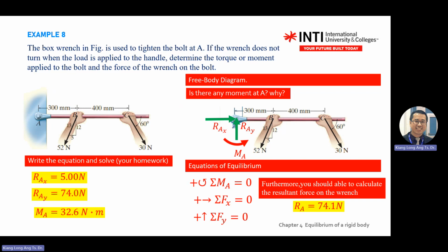We'll give you further instruction. You need to find resultant in your answer. So after you find Rx, Ry, square this one, square root, you get the resultant. Use the tangent theta, inverse the tangent, you get the theta. Okay, so this one you get resultant, but I don't go forward after this, but you should know how to do if the question asks you to do.